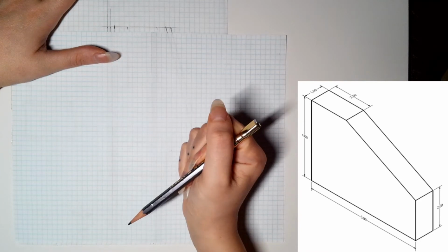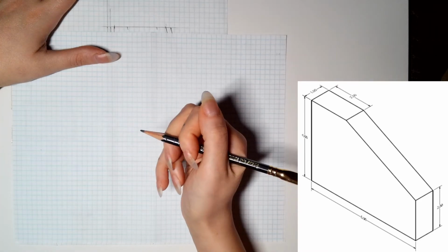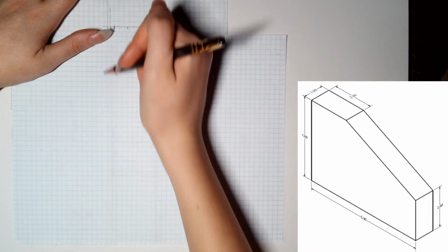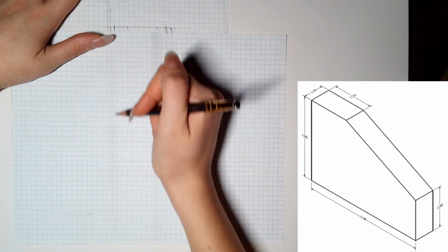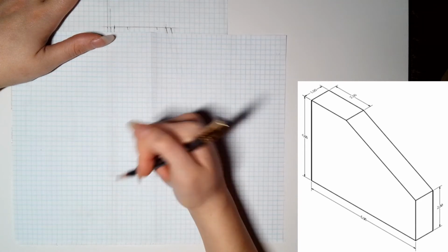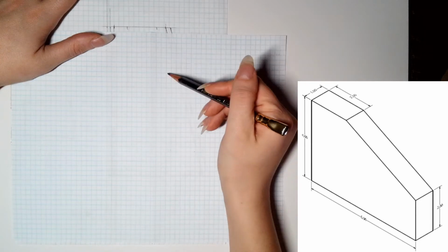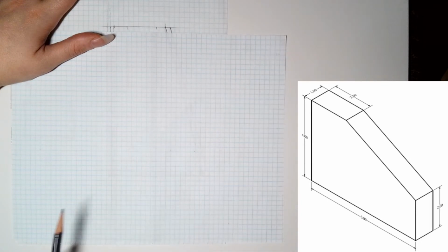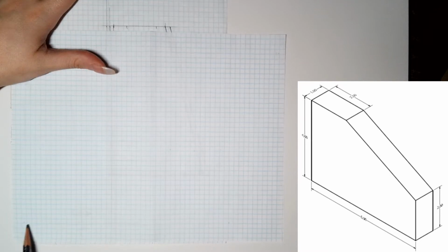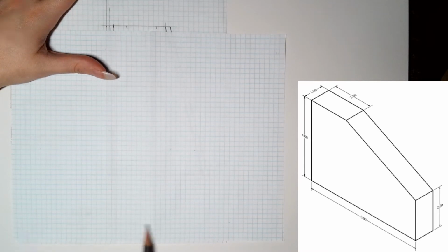Another good thing to keep in mind with your hand drawings is whenever I'm moving my pencil, you're going to notice that I move my whole arm. So I'm not just moving my wrist kind of back and forth, because that's going to make my lines wonky and curved. So I'm always going to just move my entire arm across the page. And a lot of times too, what you'll see me do is, without putting my pencil down on paper, I'll kind of just go back and forth to trace out an object. And then once I know that that's where I want a line to be, then I'm going to put my pencil down to the paper.